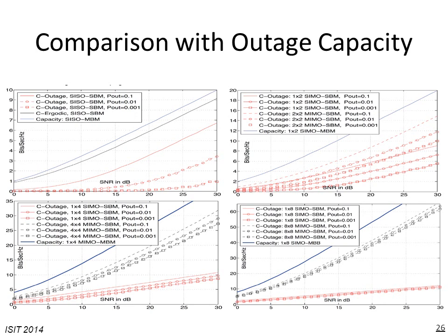For the outage of the legacy system, we have curves for different outage probabilities of 0.1, 0.01, and 0.001. As these curves show, there is significant gain from using media-based modulation, which is due to the inherent diversity that comes with the constellation, which does not require sacrificing the rate to achieve it. And it happens for the case of SISO or SIMO media-based modulation.